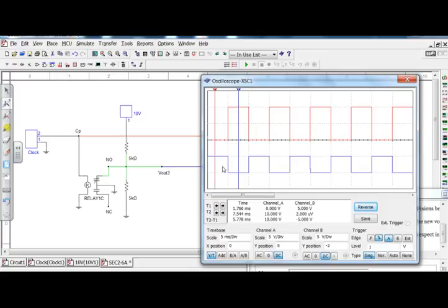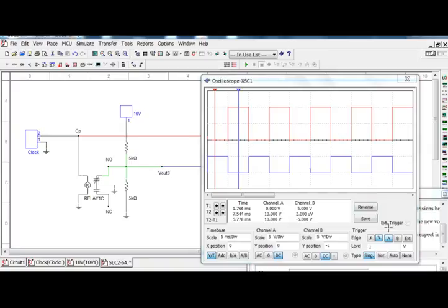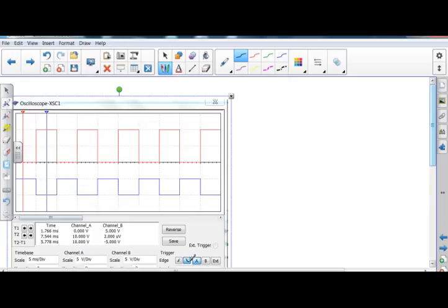The open relay contacts used to create a clock pulse. Okay, 1. Measure the voltage level of the clock pulse and voltage 3 with the oscilloscope. Note the relationship between the two waveforms. Okay, so there it is, all measured. I don't have to write anything down. So that's my A answer.